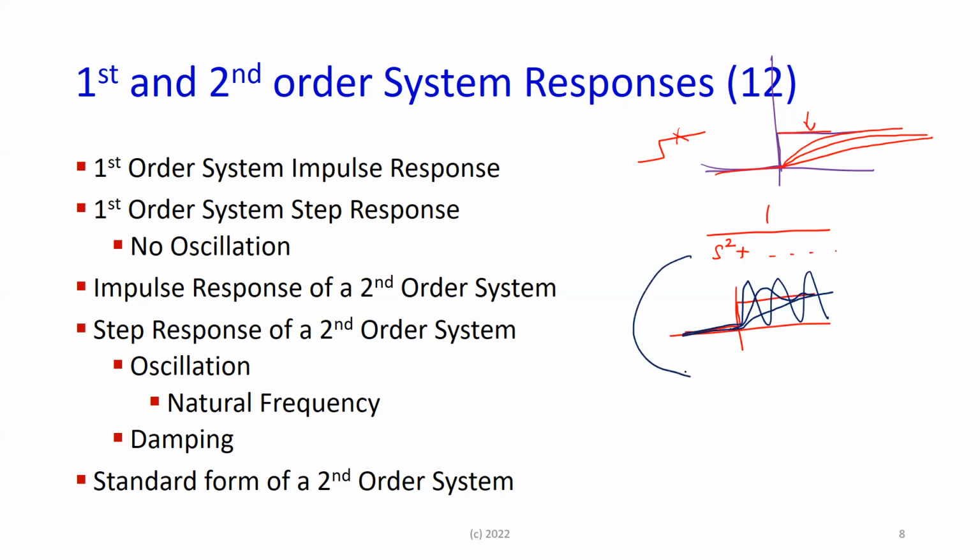The second order response leads to complex poles. Complex poles, or complex solutions in the Laplace domain, lead to cosines and sines. So sinusoids oscillate. Once you have a second order system with complex poles, you're going to have oscillation, because it's sinusoids and cosines that are created. And whether the sinusoids or cosines die out is a result of another thing that we saw called damping.